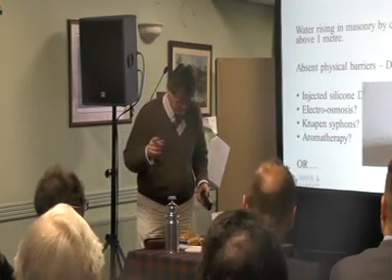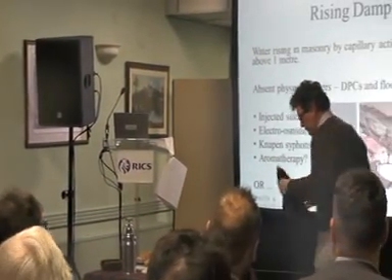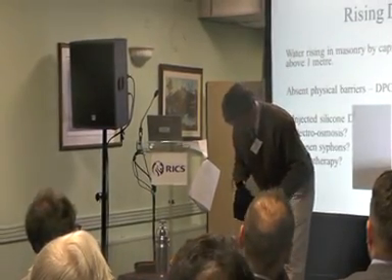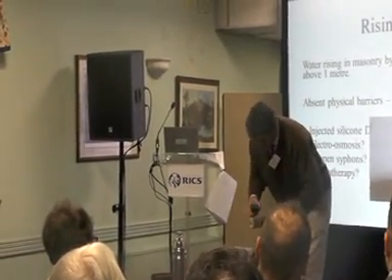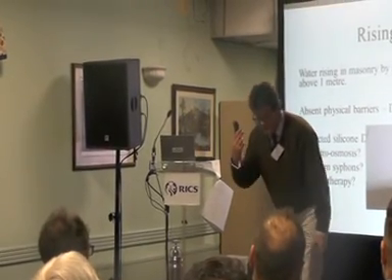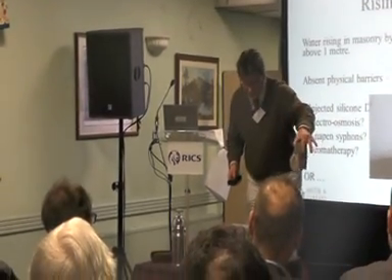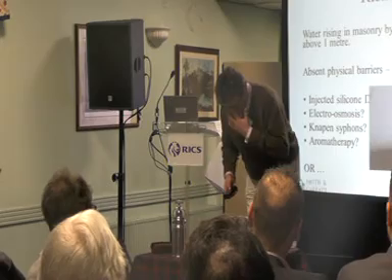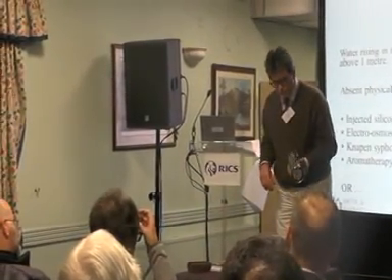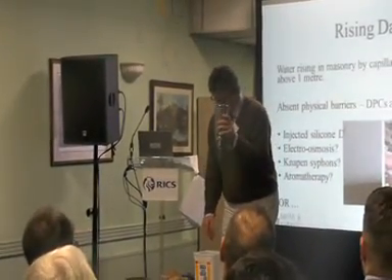Now, where did that block get to? Right. This is actually not from a coal mining area. It's from the Scottish borders, but it's made with ash. Ash contains carbon. So my meter tells me it's screamingly damp when it isn't. It's perfectly dry. Lives by the stove in my office, just for days like today. So, you need something that's in between the laboratory test and the handheld meter, the speedy.